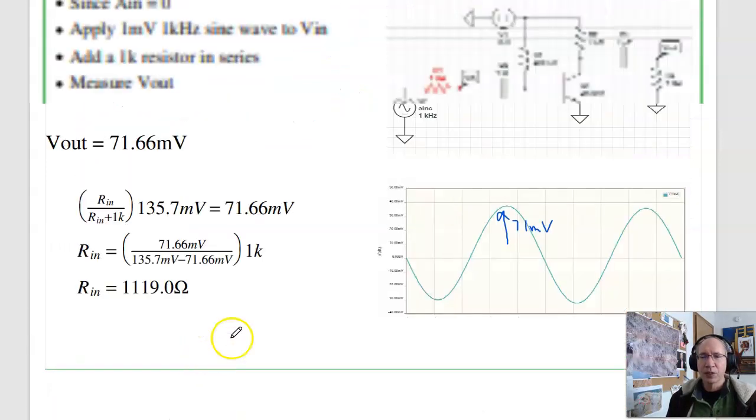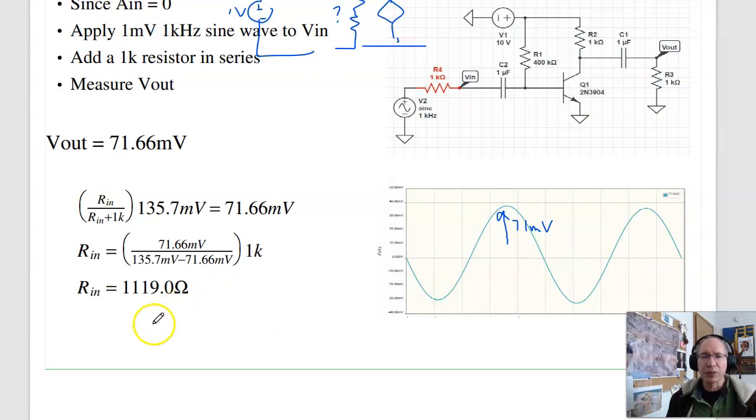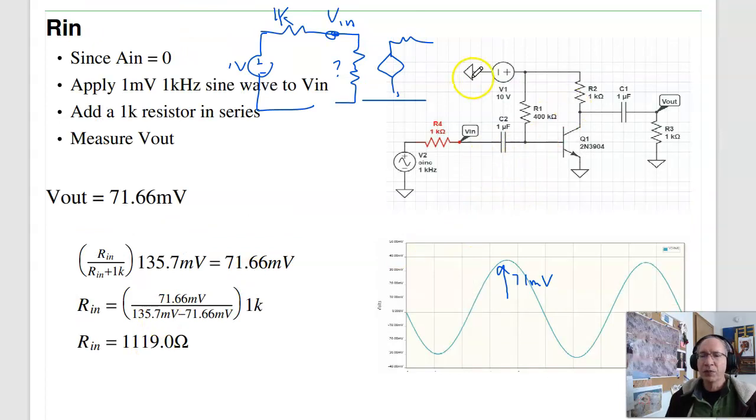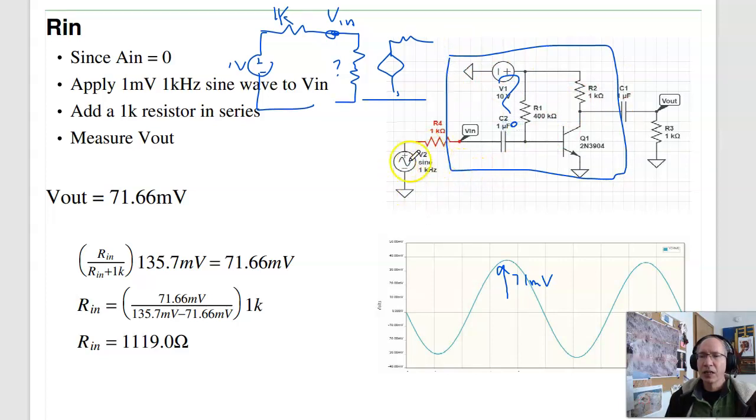So experimentally, I found the two-port parameters. And in the lab, you'd do the same thing. Run 4 different experiments with your circuit. Again, I don't really care what this is, some black box. With those 4 tests, I can tell you what it looks like at the input and what it looks like at the output, and it'll be a two-port parameter, two-port model.